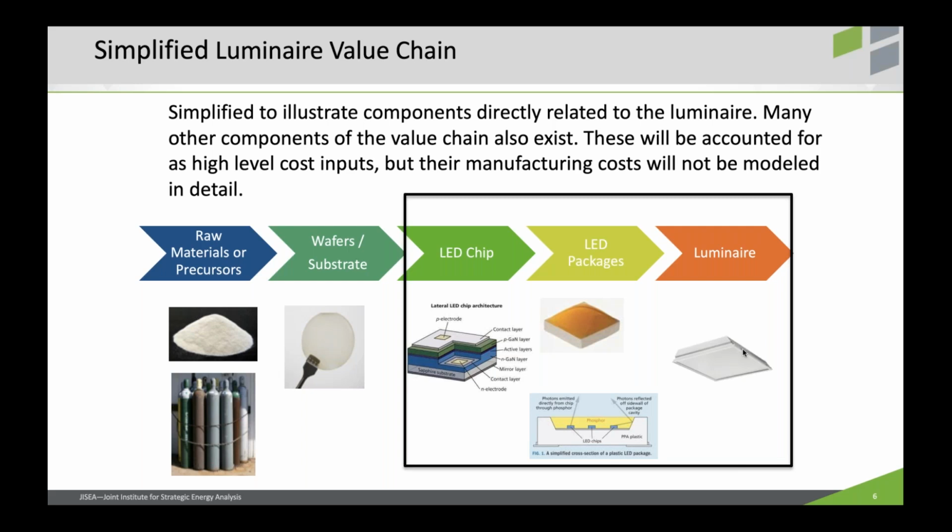Your process for an LED-based luminaire begins with LED manufacturing, which consists of growing the LED wafer, with the growth of the LED on the wafer by metal organic chemical vapor deposition. You then process the LED wafer by a conventional semiconductor process and separate it into individual LED chips. The next step is you put those chips into LED packages. Depending on what that package will be used for, you will use anywhere from 1 to upwards of 8 chips. And then you deposit phosphor materials.